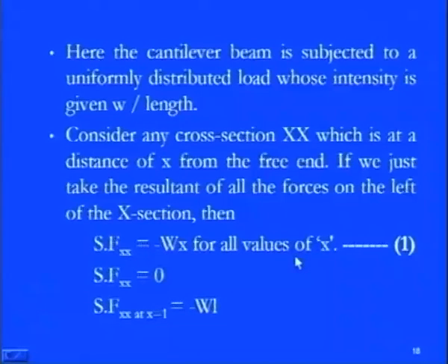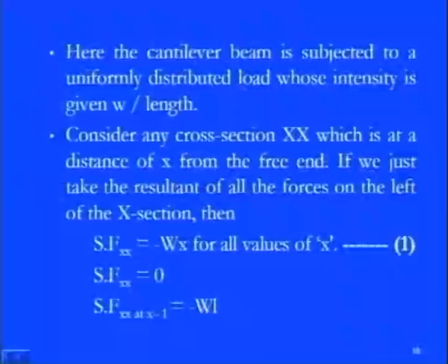If, starting from x equals 0, there is no shear force. So, if I am saying that the shear force at the section at the starting point, where x is equal to 0, is always 0, and it has a maximum value where the reactions are coming, at the top of A. So, the shear force at x equals L is equal to minus w into L.